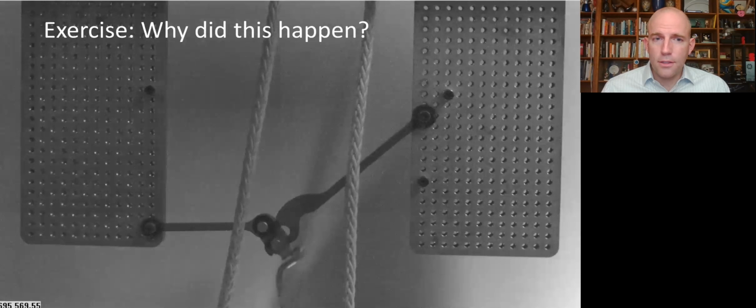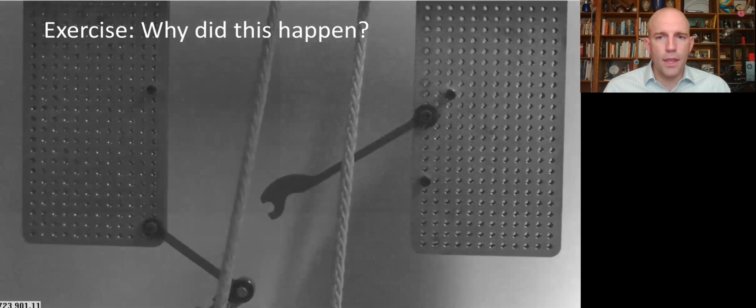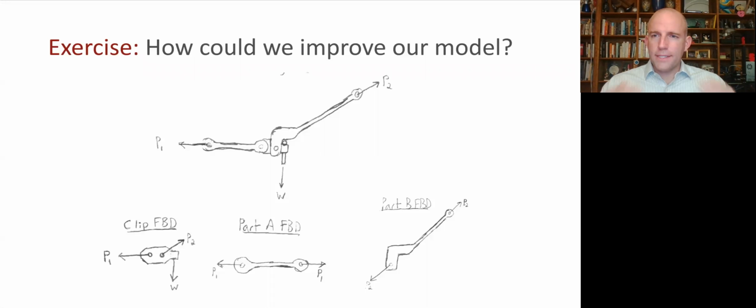All right, do you have a guess, some reasoning as to why that might happen? Well, sometimes when we see something deflect significantly or move a lot from its original orientation, that's because it wasn't actually held in place. It's not under static equilibrium. And what we're going to find out in this case is that's happening. And you can see from these free body diagrams, which were produced by the designer, evidence that static equilibrium is not possible. So now I'd like you to take a look at these FBDs and see if you can figure out what is the argument that you can't get static equilibrium.